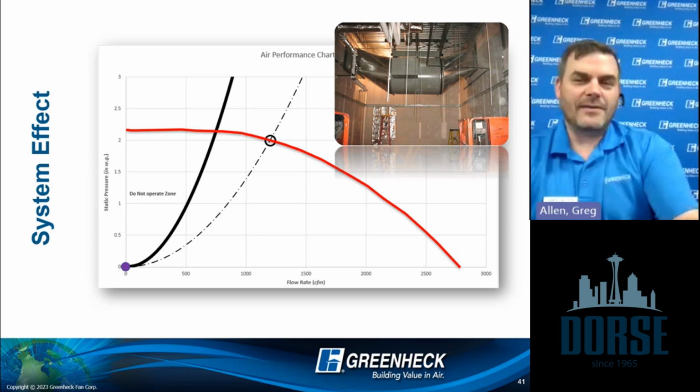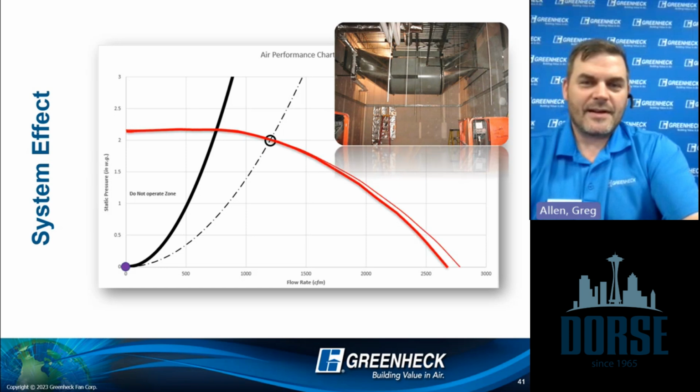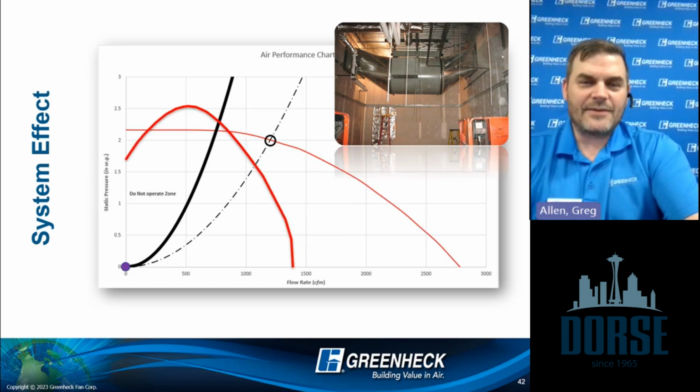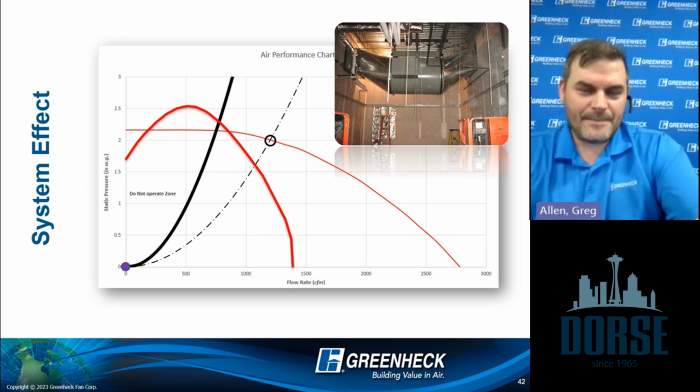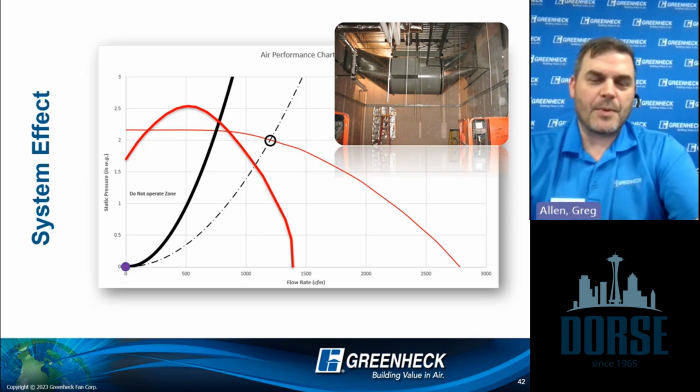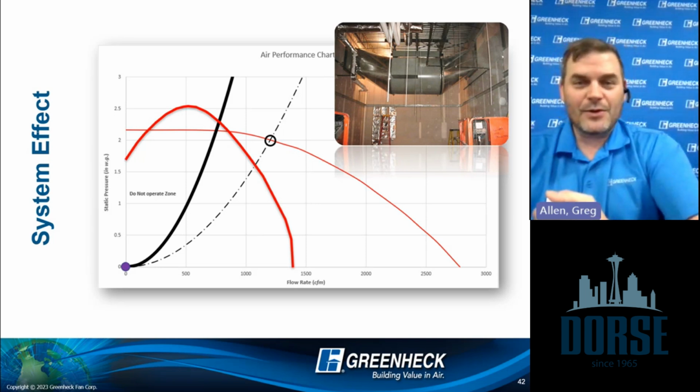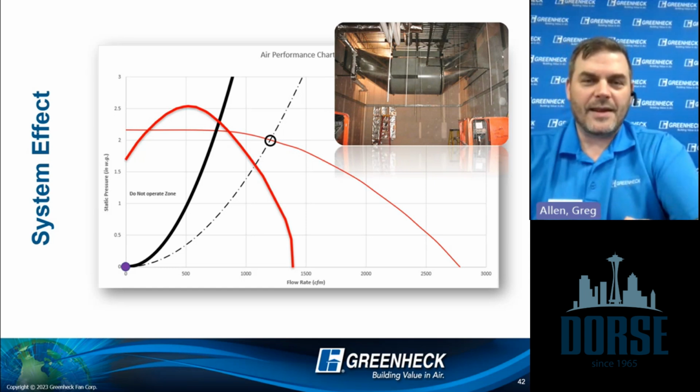And this fan curve, let's kind of make it a little alive here, actually does not even look the same anymore. It looks completely different. And the point that I impact between my system resistance and my new fan curve is going to show quite a loss of CFM.